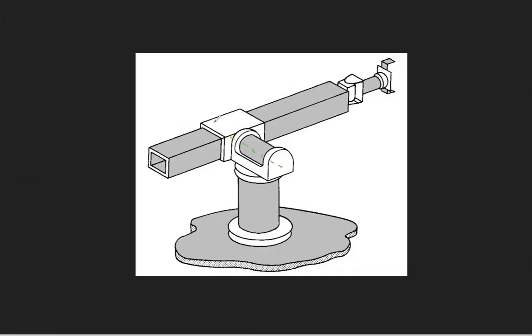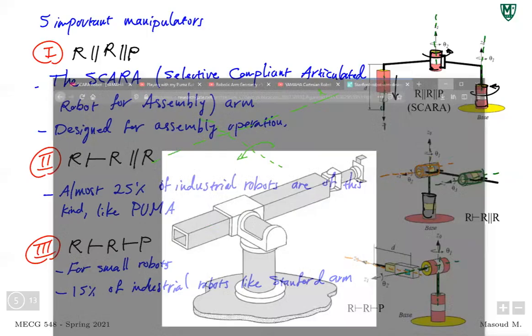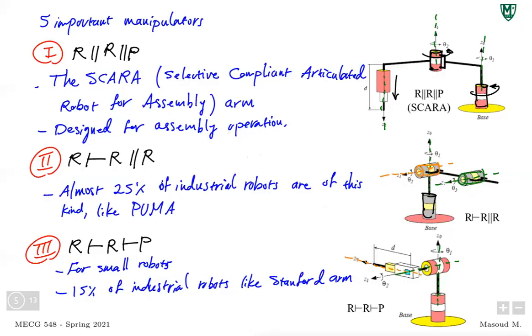So this joint is a revolute joint, right? The whole last piece of this arm, this link, can rotate around this joint, and then for this joint, the axis is here. So the two axes are intersecting. So you have orthogonal, orthogonal, orthogonal, but revolute, revolute, prismatic. I just got totally sidetracked by another line of thought. All right, so that's it.